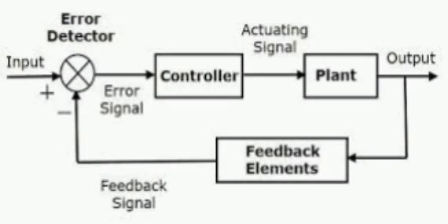Transient and steady state analysis depends on the order of the system. The order of the system is obtained from the closed loop transfer function, that is G of s by 1 plus G of s H of s. The highest power of the characteristic equation, that is 1 plus G of s H of s equals 0, determines the order of the control system.